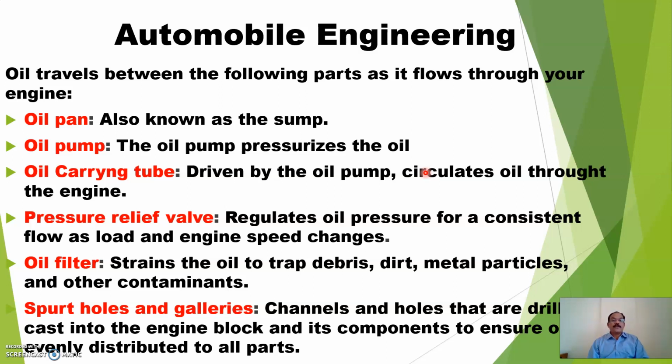Then sometimes a pressure relief valve is required in some engines to regulate the oil pressure for a consistent flow as load and engine speed change, because you cannot supply constant oil if the engine speed is low; the lubrication required will be low.